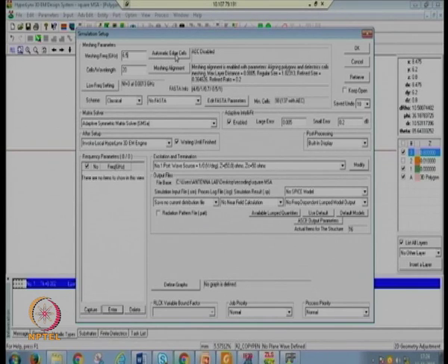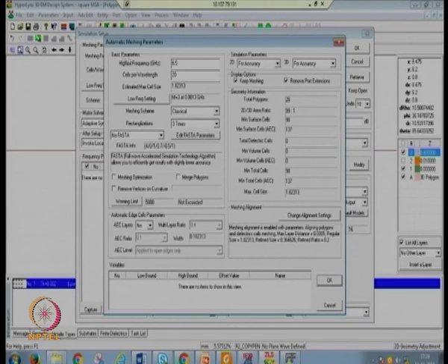Now, the second option is automatic edge cell. Automatic edge cell means that it is providing you a meshed structure, and the meshing towards the edges will be finer, which will increase the accuracy of our results. So, we need to enable it. We check here. Now, you see the frequency we defined is given here. The next option is cells per wavelength. This is how many cells we are dividing per wavelength, that information is given, and the low frequency part I have already told you.